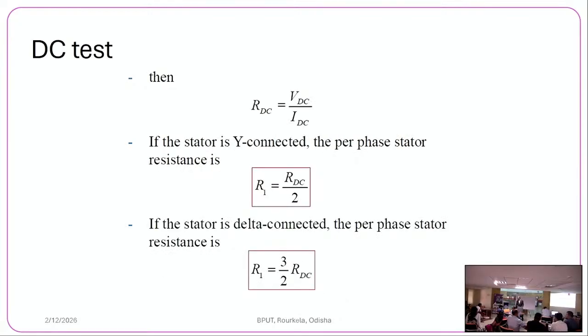Multimeter also you can directly measure that. Multimeter also you can use, but with a multimeter you apply only 3 volt or like that. With that small voltage, you don't get an accurate result. But still it can be done.